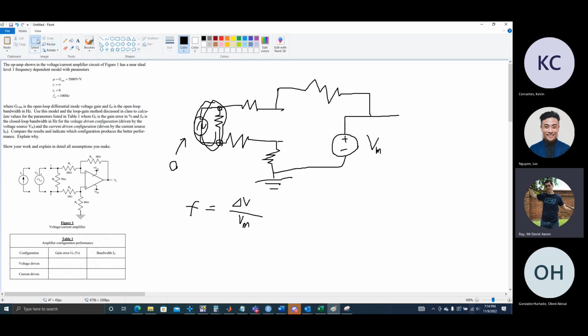So what this is actually saying, this kind of goes back to that first part, is that whenever you connect 0 volts to this, you're saying that this is 0 and that this is 0, or that they are the same points. And so just like a straight line, if this is 5 volts, and then this is 5 volts, and then this is 5 volts, any place minus the other place is still 0, and therefore it's a short.